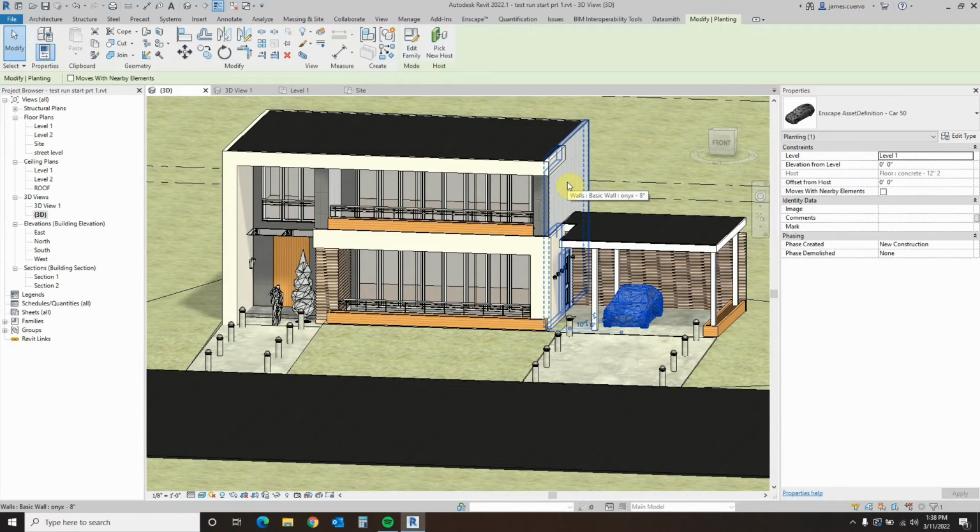Now it is time to import some light emitters into the Revit, but in order to do that, we must first turn on light emitters in the Revit viewport. Following this, we will, in this case, swap out an existing Enscape light fixture for one with a light emitter. The light fixture that we will be swapping out would be these right here.